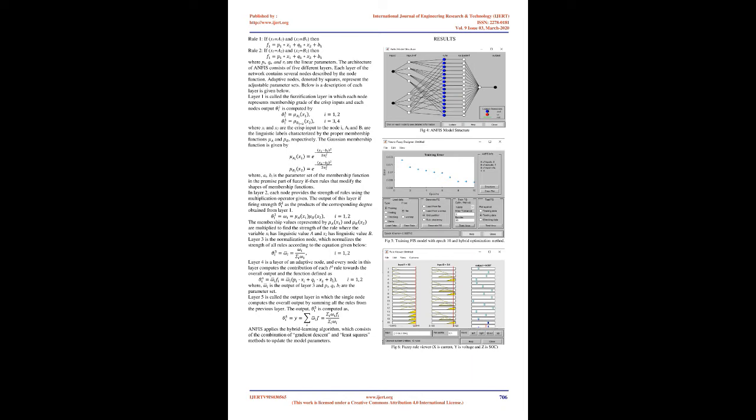The input variables are fuzzified so that the degree to which they fit each of the fuzzy sets is established over membership functions. Next, an AND or fuzzy operator is used to combine the inputs resulting in a single number. Next, the rule's weight is set before the implication that is implemented toward each rule. Then all the fuzzy rules are combined and evaluated. The outputs are aggregated by aggregation methods including max, maximum, probabilistic OR, and sum, simply the sum of each rule's output set. Thus, the outputs of each rule are combined into a fuzzy set that needs defuzzification.